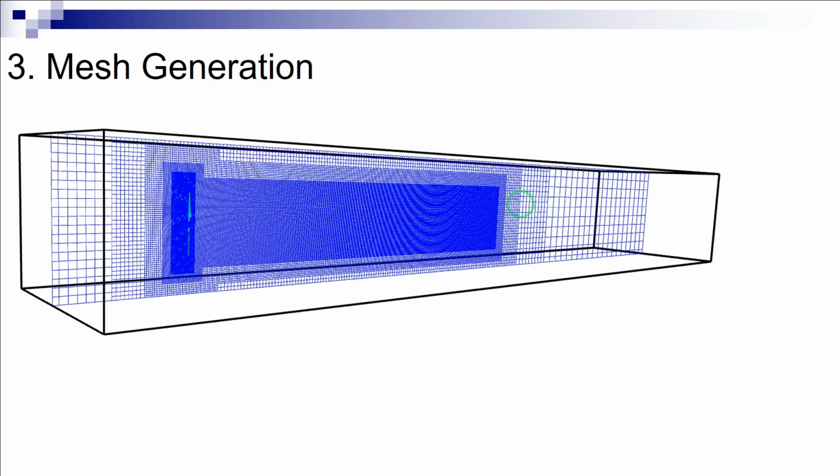3. Mesh generation. To generate the CFD mesh, the computational domain is divided into two regions where cells with different shapes and orientations are used: the region close to the wind turbine rotor and the region far from the wind turbine rotor, as shown here. The region near the wind turbine rotor is more critical for CFD mesh generation as the quality of mesh in this region directly impacts several important aspects of the CFD simulations, including the stability of the simulations and the quality